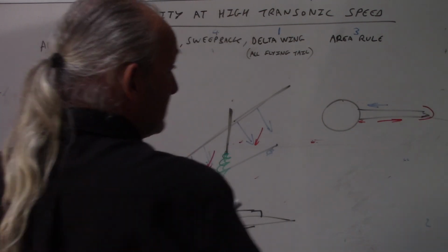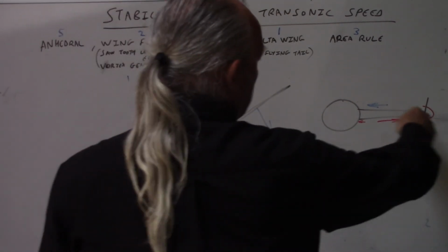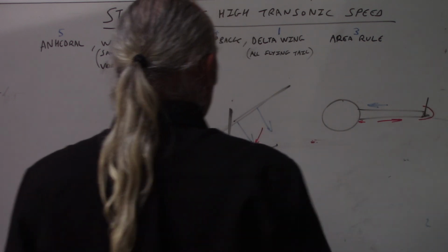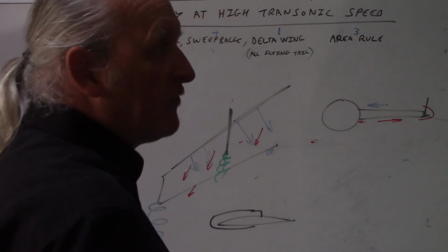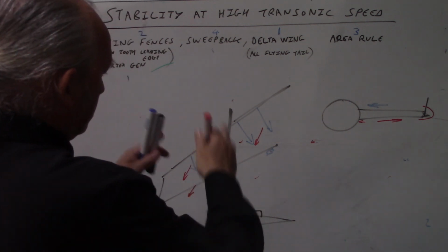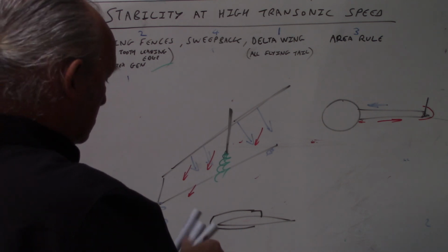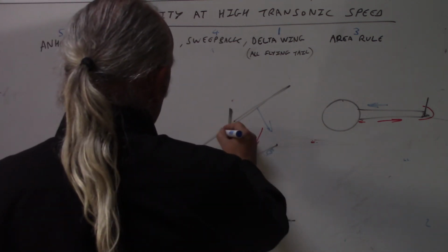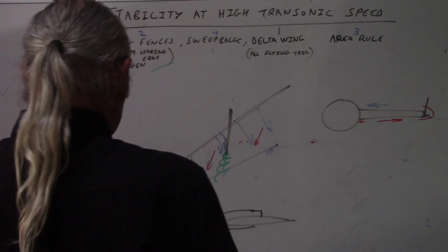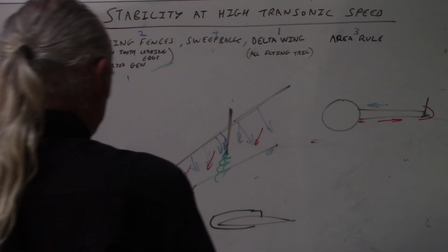That's why we get winglets. So winglets can be used to prevent that. It stops the high pressure air coming round, and the low pressure air stays where it is. Wing fences act the same as winglets. Before we had winglets, we had wing fences. They're there to just cut down on that span-wise flow a little bit. So it stops it happening here. It won't allow the low pressure air to go that way, and it forces it to go that way. And it also straightens out the flow a bit.